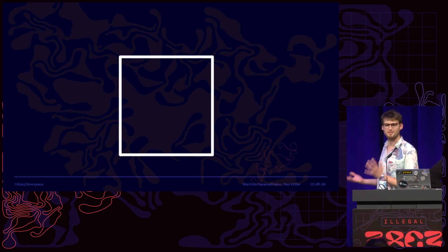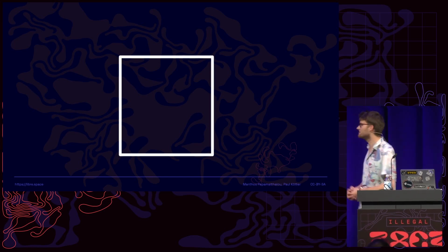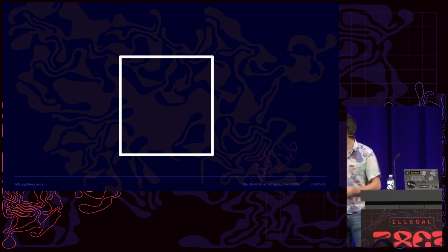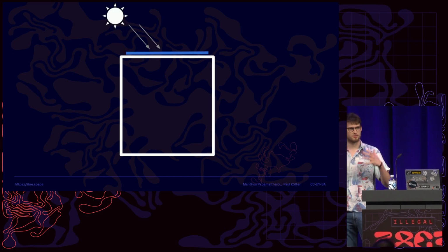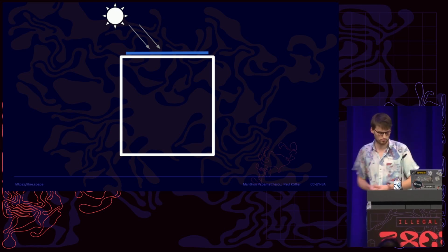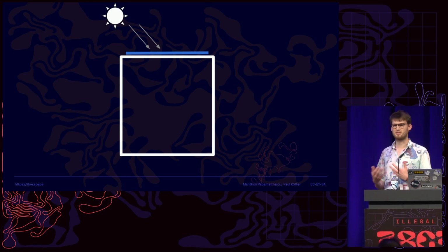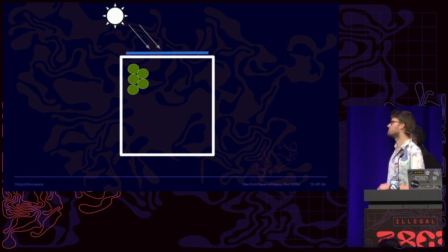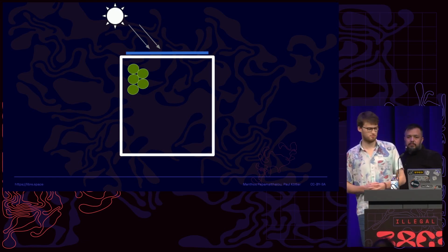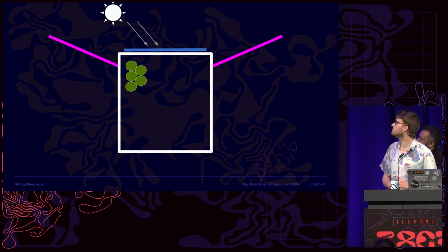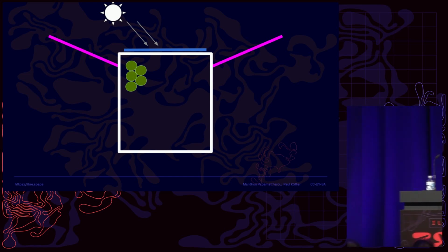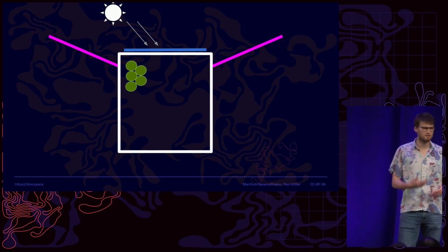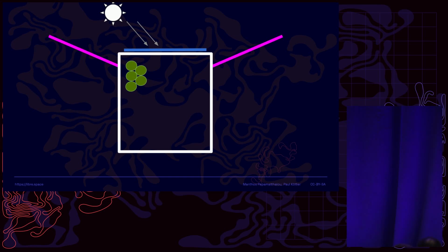So let's talk about satellites first. The very basic thing you need for a satellite is some kind of box, something you can mount stuff to. The second most important thing, I would say, is solar cells, so you can get power for everything that you want to do. But because you're sometimes also on the dark side, you need batteries to store power and use it then. The last thing that is very, very important is communication. Because with communication with Earth, you can decide what you want to do with the satellite, and the satellite can send you back data. So we have 2 antennas and a communication subsystem that is also inside the satellite.